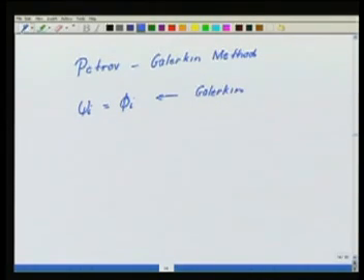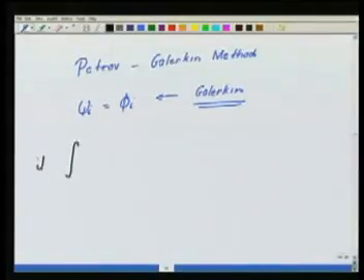And in fact, we can do the integration by parts and get the weak form, and we saw that whatever we have done is essentially using this Galerkin. Another way of doing this, which is quite popular in fluid mechanics computations, is I say that I will define a functional j dx.